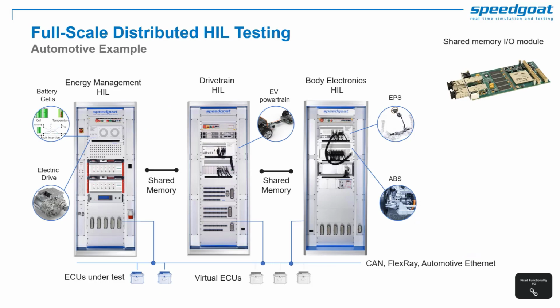For instance, in this example of an automotive HIL setup, the various simulators are interconnected through shared memory I/O modules. Shared memory lets you synchronize execution across nodes and exchange data with very low latencies.